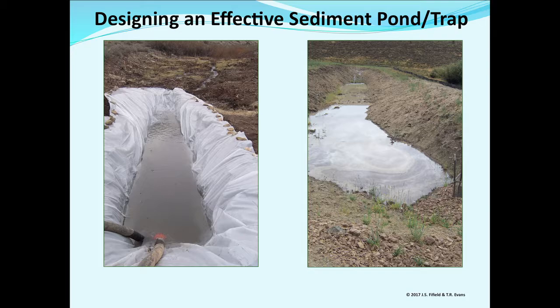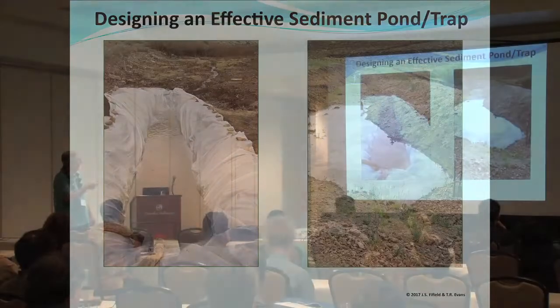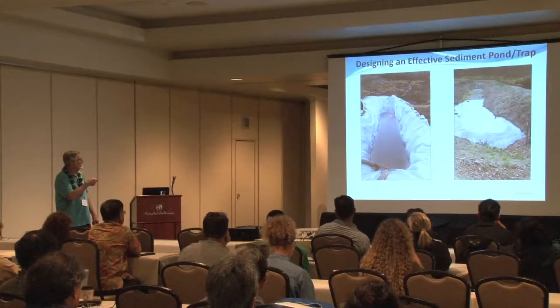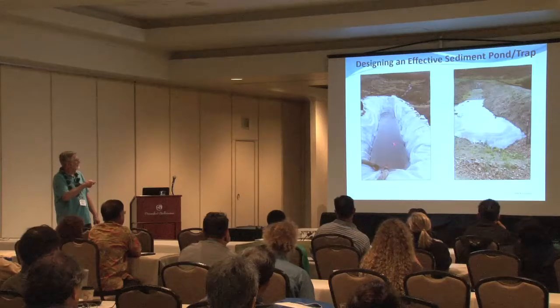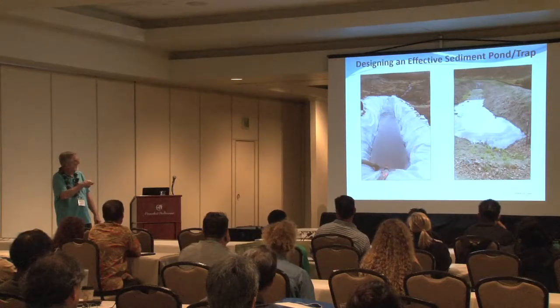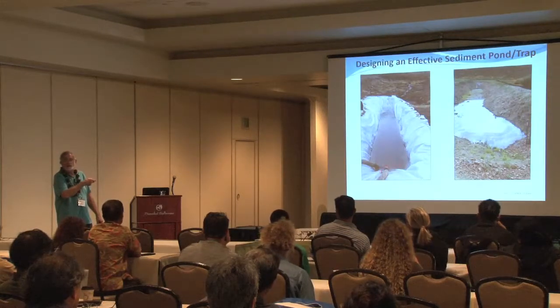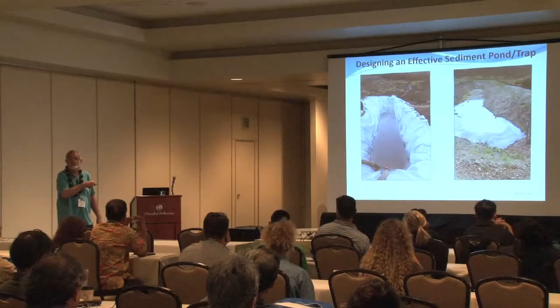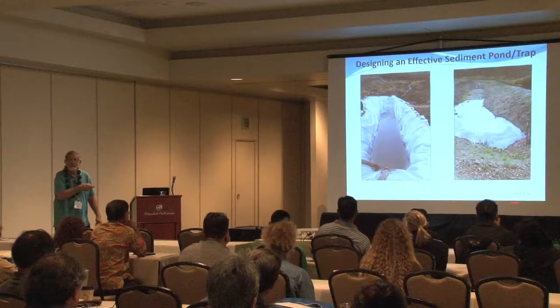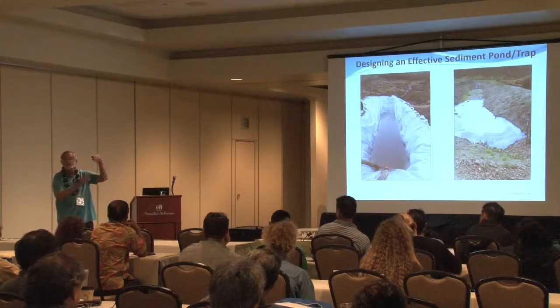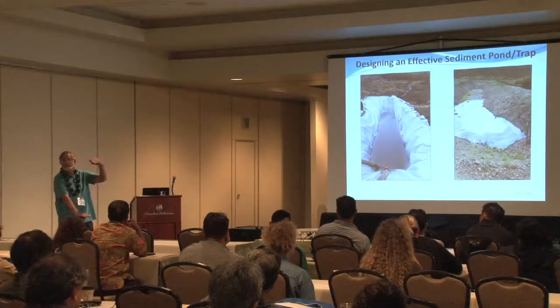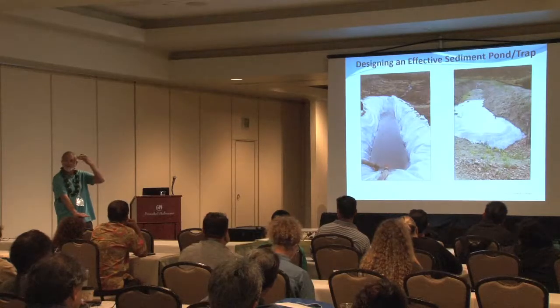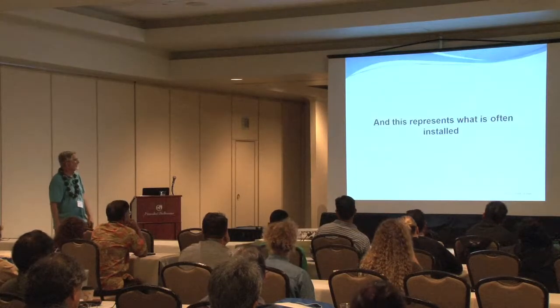This was a temporary one. Contractor came up with that idea. He says, look, all I got to do is line this thing, and then we can have water pouring there. It'll take care of it. And he says, we'll pump the water out. And the only thing I did on it, pump it from the top of the pond. Why would I pump it from the top and not the bottom of the pond? Where's the sediment going to be at the most? Top or down here? These are logical things that come up.